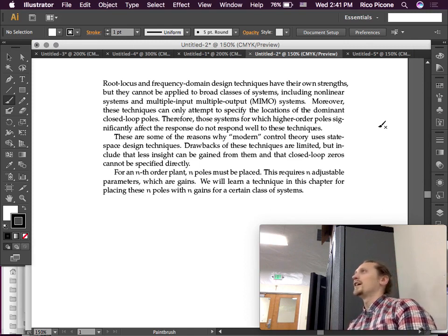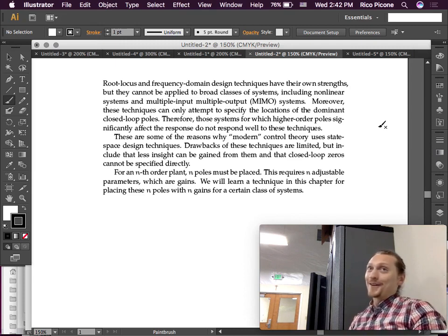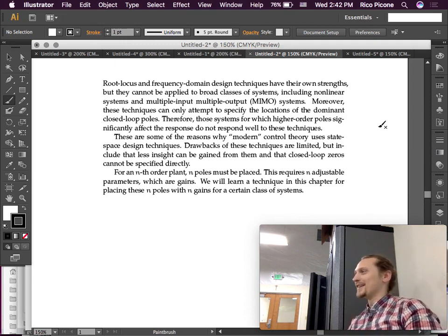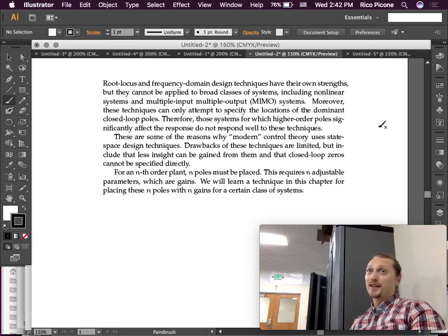Note that in the following, I don't have a lot of discussion of the control effort that goes into this. But that is a key, as the controls group in simulation has discovered. You can say you're going to have a controller that has these gains or whatever, and that's great. But if your controller can't supply that much power, then it doesn't matter if your theory says that that's the right controller for you. The real system's not going to respond like that.